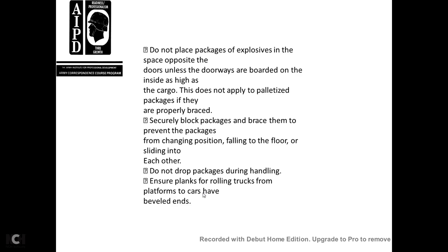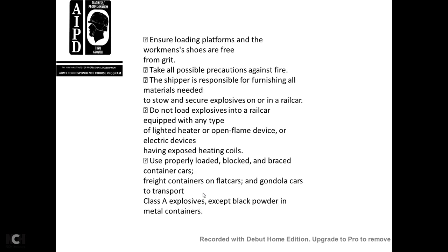Secure block packages, bracing them to prevent the packages in the shipping position from falling to the floor and sliding into each other. Do not drop packages during handling. Ensure planks for rolling trucks between the platforms and cars have beveled ends. Ensure loading platforms and workmen's shoes are free of grit. Take all possible precautions against fire.